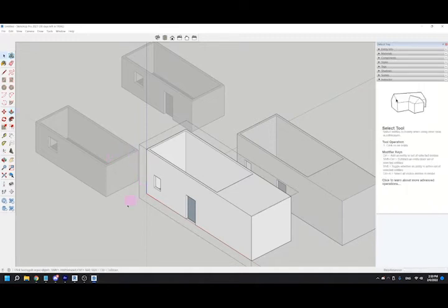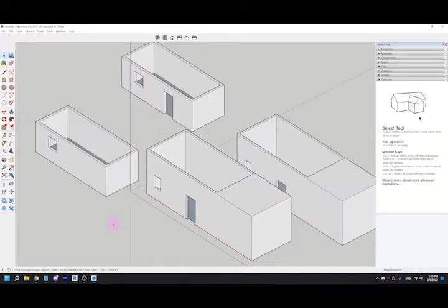But groups and components are super important for when you are going to be modeling things with more than one part or piece inside of it. And so your big SketchUp project is going to have to include multiple components, multiple different features inside of it. And that's where having things either grouped or made into components is going to make it much less of a headache. So once you put your basic structure together, grouping them is going to be a huge lifesaver for you that I super duper recommend you do.